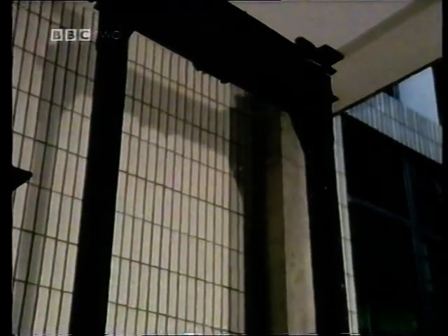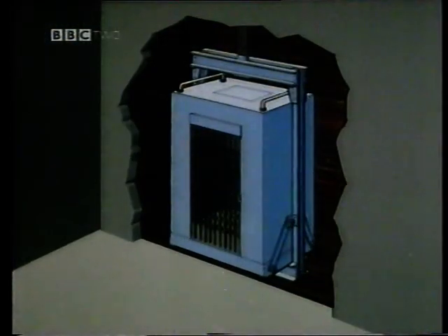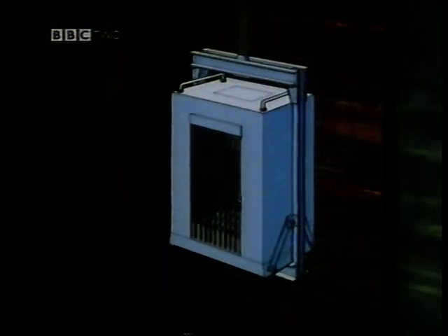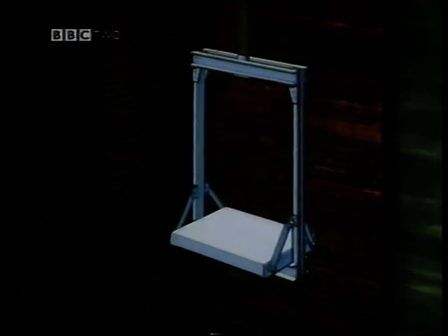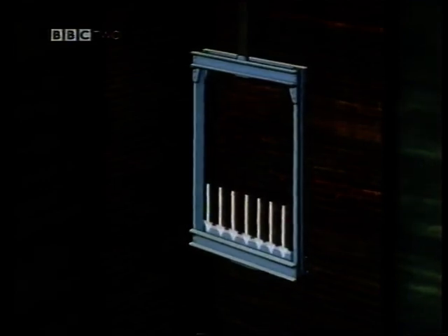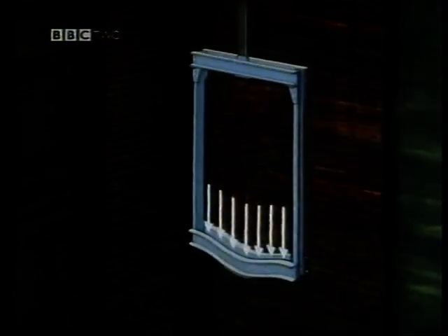Another problem that your students may be interested in from the mechanical design point of view is the construction of the car frame itself. This is subjected to a whole series of different loadings. The normal structure of a lift car is of a box-type arrangement, contained within a frame. The base of the frame supports a platform which carries the passengers. The platform effectively spreads the load, so that the cross-member supporting it is in effect a beam under a uniformly distributed load. So this beam has to be designed for stresses resulting from downward bending.